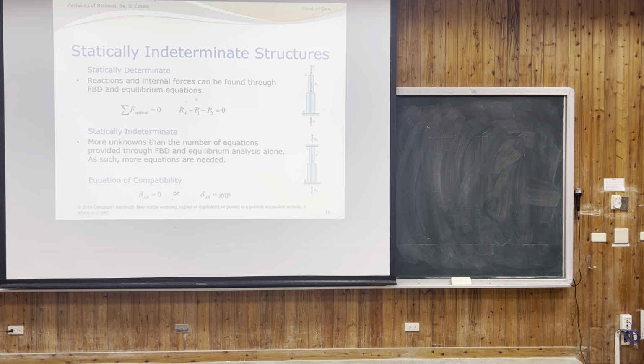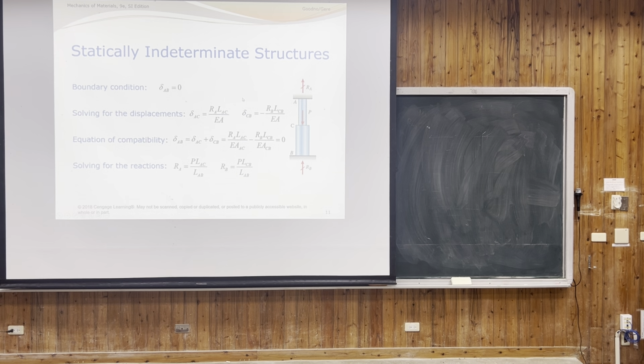So do you guys know the difference between statically determinate and statically indeterminate? Just a different amount of unknown equations, right? For the indeterminate it is more than 3, but the determinate is just 3, right? Yeah. So when dealing with indeterminate questions, you have to somehow write the equation of compatibility. Hard to pronounce. Compatibility.